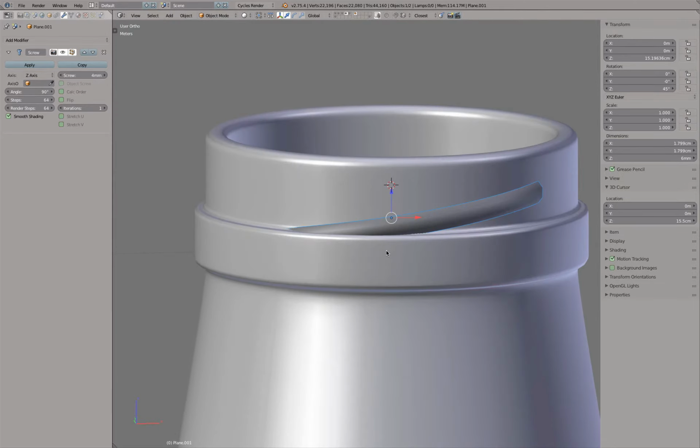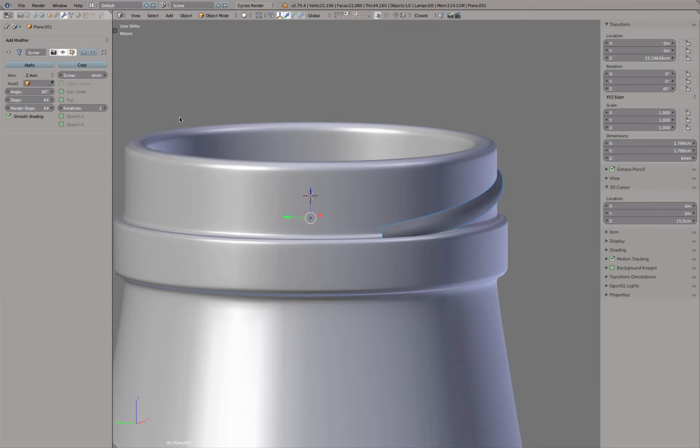Well, this is really 3 millimeters. That looks a little bit too strong. Let me measure this again. Nope, it's actually not 3 millimeters. My caliper was incorrect. It is actually 2 millimeters. Okay, so GZ .001, 1 millimeter up. Okay, unfortunately this piece sticks out again. Okay, 5 millimeters.